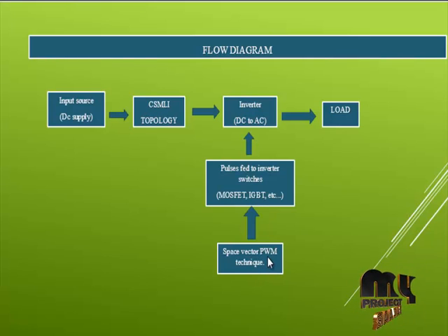Using space vector PWM technique, the pulses are generated and fed to the inverter switches through the gate driver circuits, and space vector PWM technique is more efficient compared to the other PWM techniques. After conversion of DC to AC, that AC supply is fed to the load. Here we are using RLC load in our product.